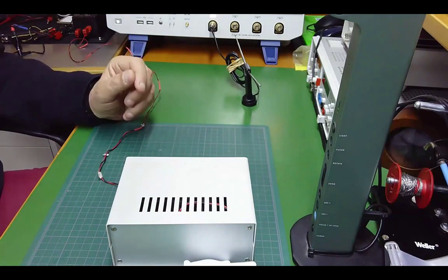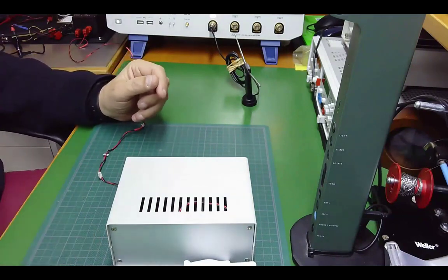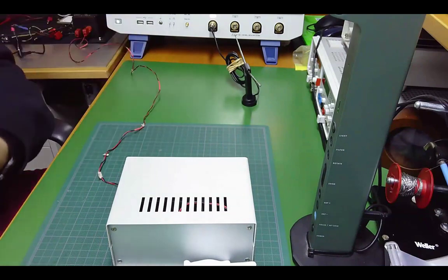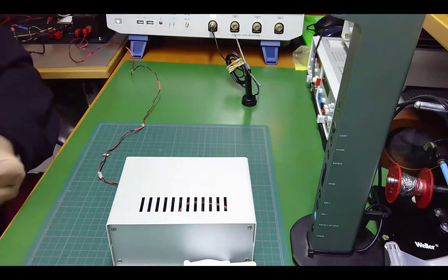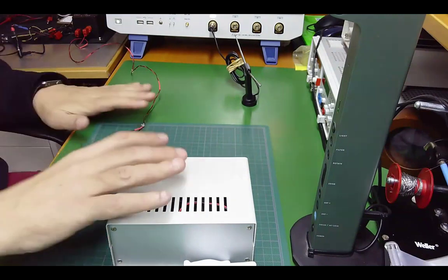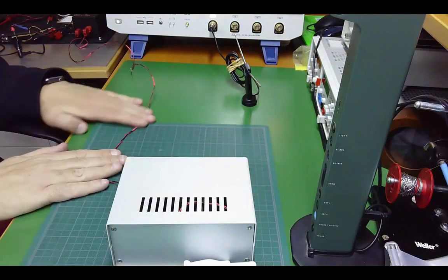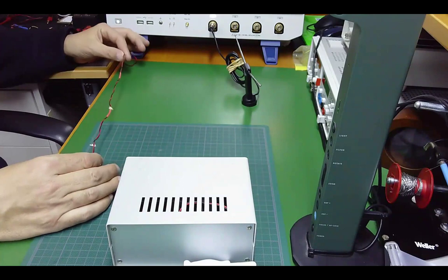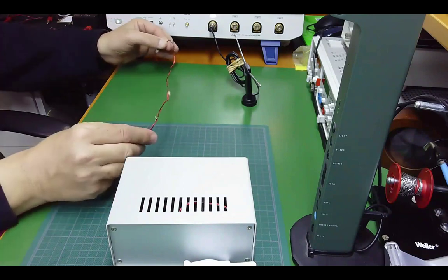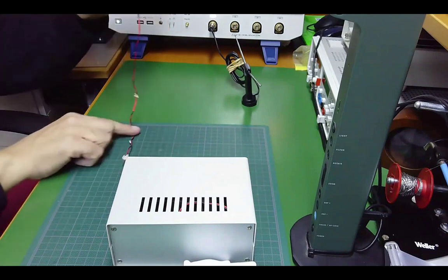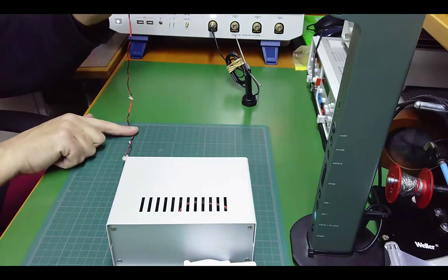If you put the antenna at 1 meter from the device under test, you can pick up from a small area of your product, for example, from a display or from a small PCB, a signal that theoretically you will not be able to radiate to the far field. Anyway, in my product, I am going to consider that the most important radiating element is this cable. Look at this, the cable is horizontal and it's not vertical. If the cable is vertical, we'll be radiating vertical electric fields.